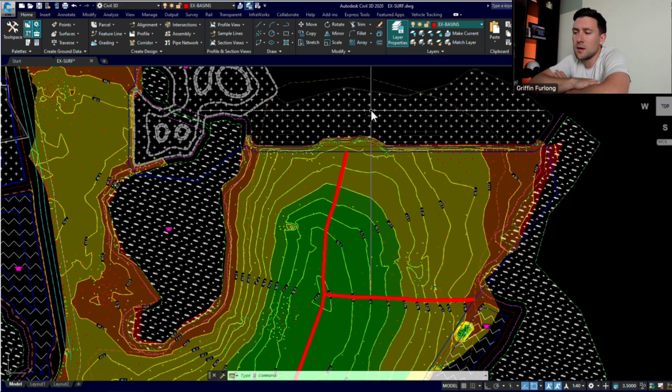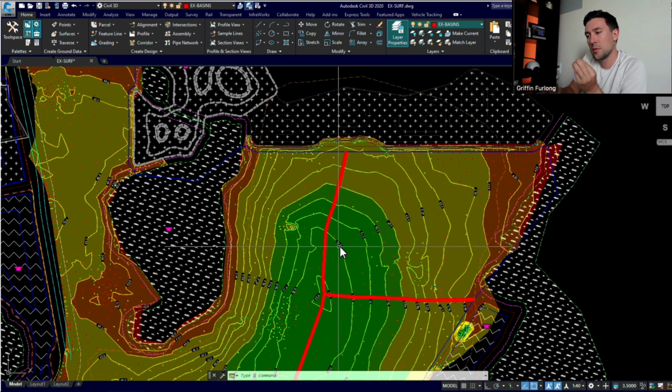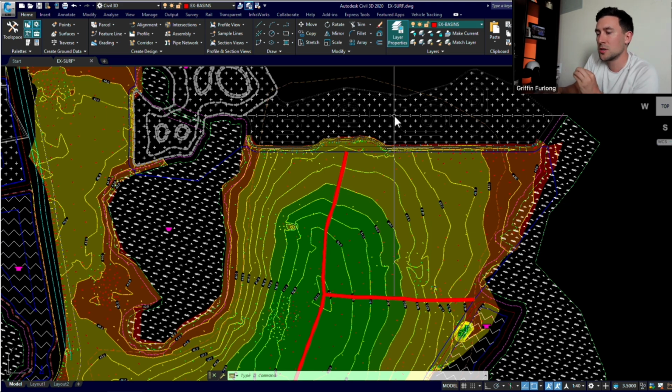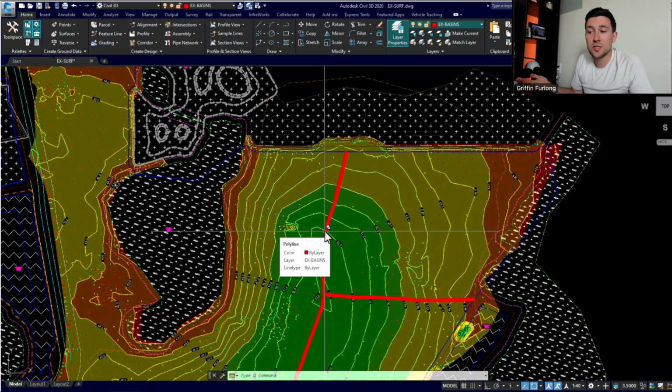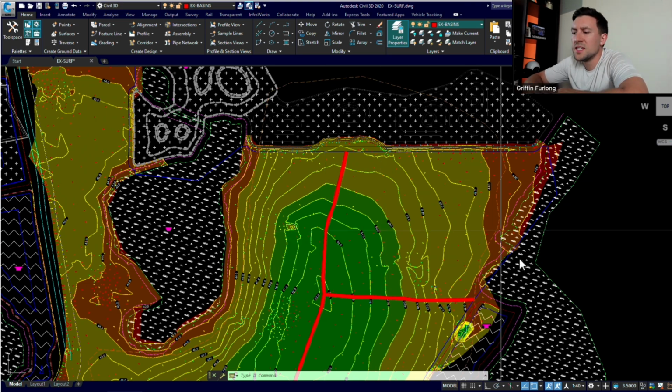So I think, when you run into this situation, it's best to isolate the basins, because I want to know exactly how much water goes to this wetland and how much water would go to this floodplain mitigation pond. So perhaps my initial pass of this line could potentially change depending on how I'm trying to analyze this existing conditions map. Think of each of these as a storage unit. This wetland is a storage unit. We want to know how much water is going to the wetland, and this floodplain mitigation pond is a storage unit. What is the quantity of water flowing to these storage units?